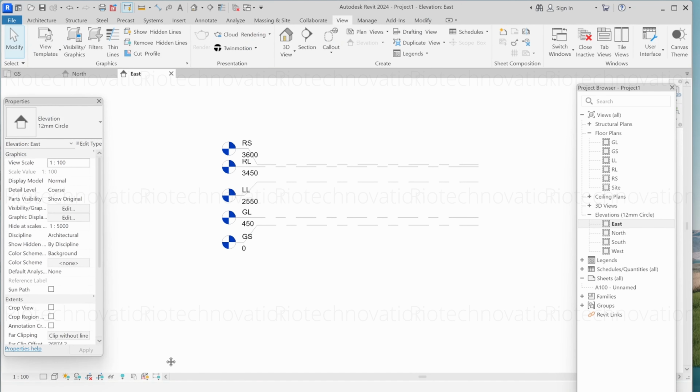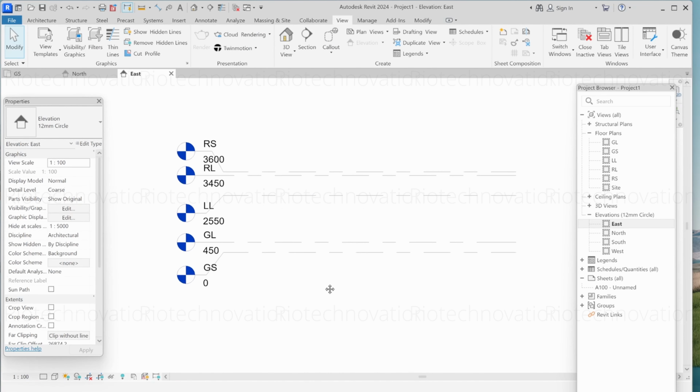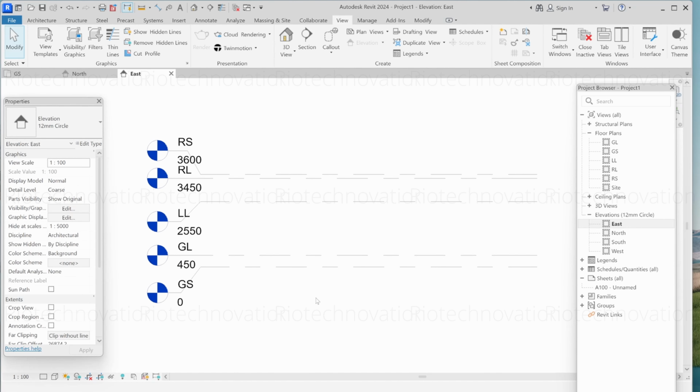Come escape. So this is how you can set the levels, which is a very important basic chapter only, but which is very important. We have to focus on this one. Make multiple level settings, multiple projects in level setting, make multi-story buildings level settings, which makes you very super fluent in this. Because we are not supposed to make any mistakes while setting levels. If you're making any mistakes while you are setting the levels, it is going to be unrectifiable, or you will suffer to rectify, because you are aligning walls, windows, so many things according to the levels.